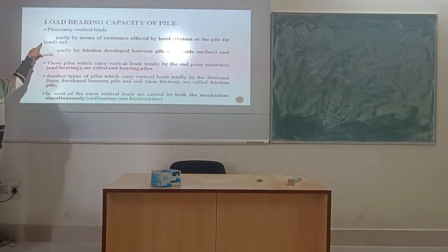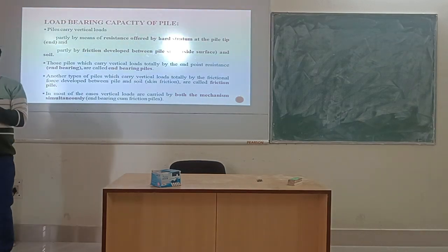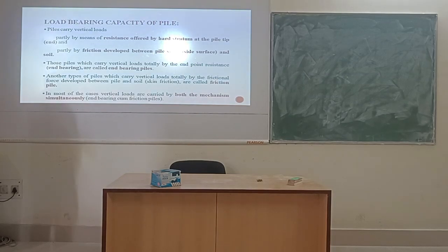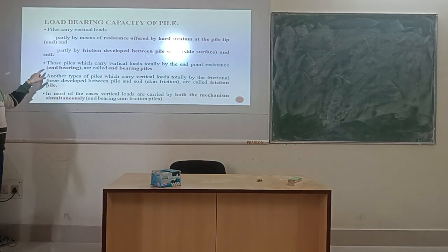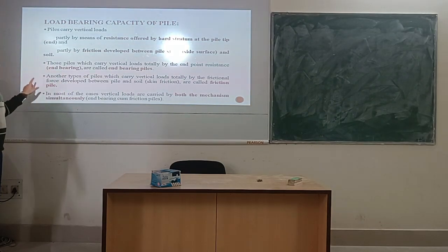The total load from the superstructure will come to the foundation, maybe a shallow foundation, maybe a deep foundation, and through the foundation that load will transfer to the soil layers. So the foundation is the mediator from the superstructure to the soil. In the case of pile foundation, there are two mechanisms: one is end bearing, another is friction.